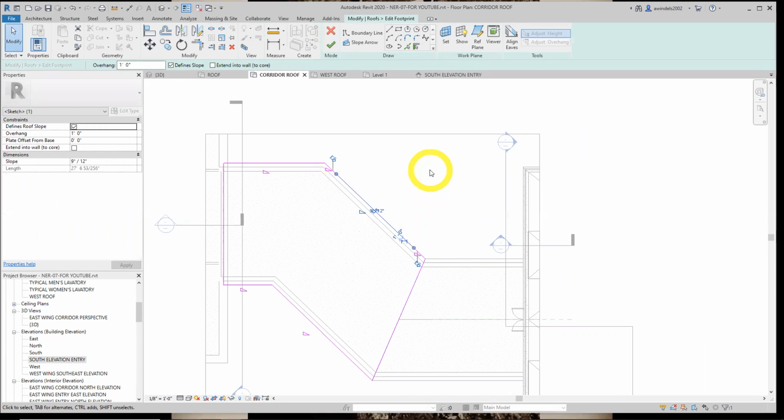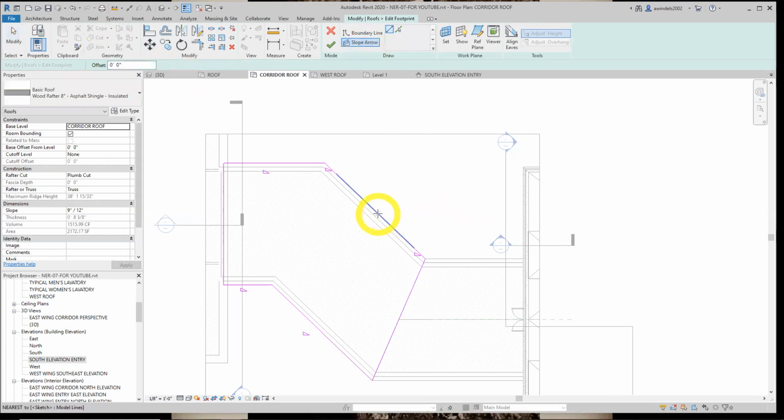We have our options bar similar to what we were messing with before when we were changing how the roof went. I'm going to deselect this now. That's the big step there. Now we have the length of the dormer established. We're going to indicate to Revit that we want it to be a gable end dormer. So we're going to have to do that by adding slope arrows into the roof. So let's start by slope arrow. And take a look on the picture on 366 on the pick areas. But also, we'll just watch me here.